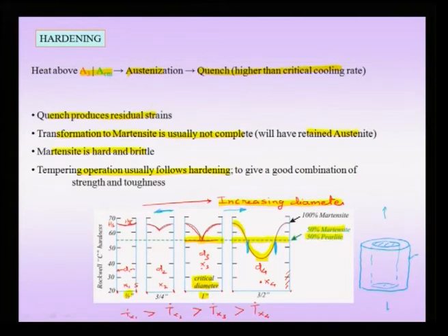So, therefore, I can only harden through sections by quenching that are below the critical diameter. That means, you are now placing a limitation on the thickness of the sections which can be hardened. Of course, the geometry of the specimen need not be cylindrical, it could be plate like, but again if you are using a plate like specimen, which of course you are seeing a cross section here, then you would note that if I choose a plate which is more than the critical thickness, then there will be a central core region which has less than 50% martensite and therefore, has not been through hardened.